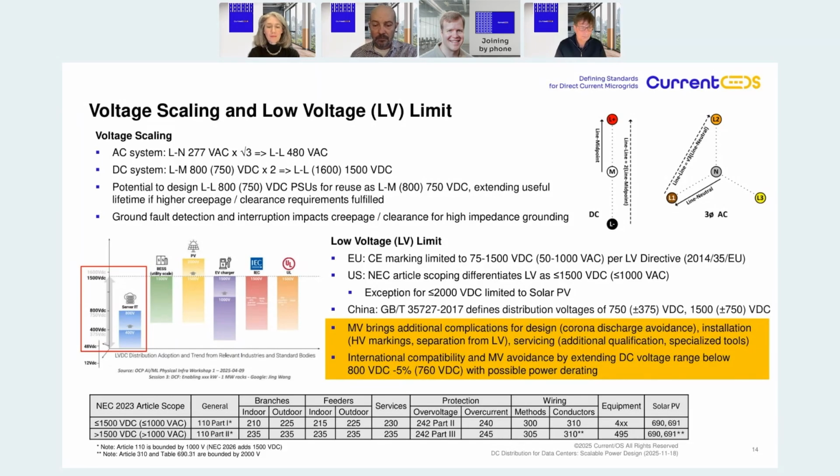So in general, if one optimizes for the max power and voltage at the 800 level, but so tightly constrained to limit, say, to plus minus 5% at 760 volts, then this could be somewhat challenging to extend further into the 750 volt space, and to potentially reuse some componentry for a plus minus 750 volt application.